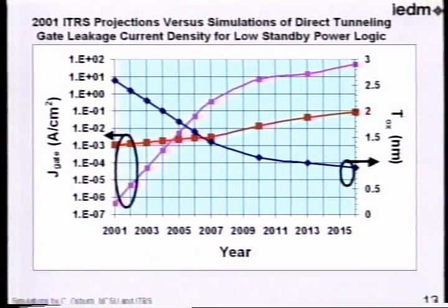So if you look at this, also in terms of gate thickness, we talked about leakage a while ago. If you look at the curves here, the oxide has been coming down, scaling down, as shown right here. And we'll see in a little bit there may be a limit to how much you can scale this because of some physics in terms of, say, a conventional planar CMOS. And then we have also the leakage shown here.